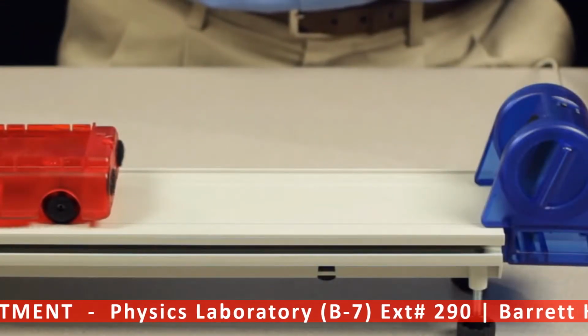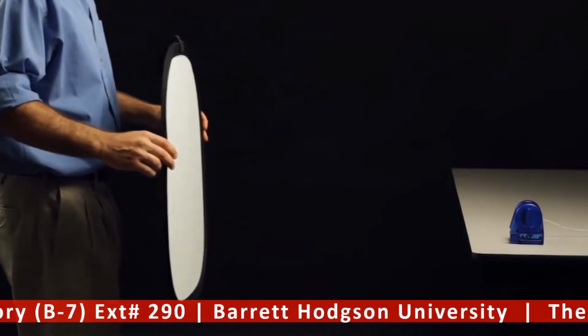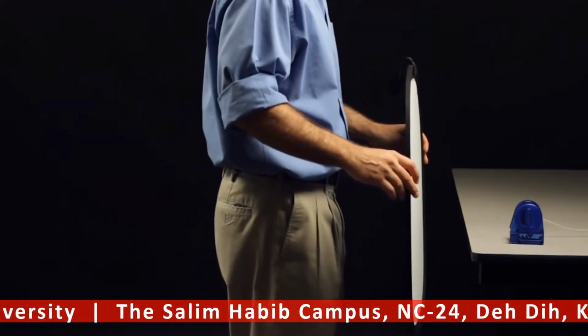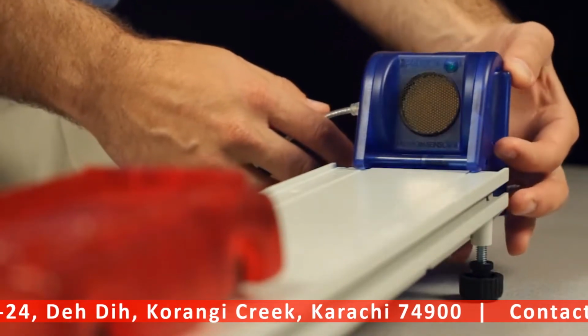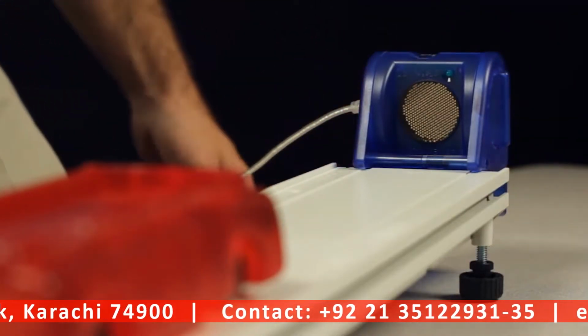Also, the sensor has a minimum range of 15 centimeters and a maximum range of 8 meters, and is sensitive to the type of surface from which the pulses are being echoed. A harder surface will generally produce measurements with less noise. When making measurements, the transducer on the front of the motion sensor should be aimed directly at the target object. Use the rotary dial on the side of the sensor to aim the sensor at the target object.